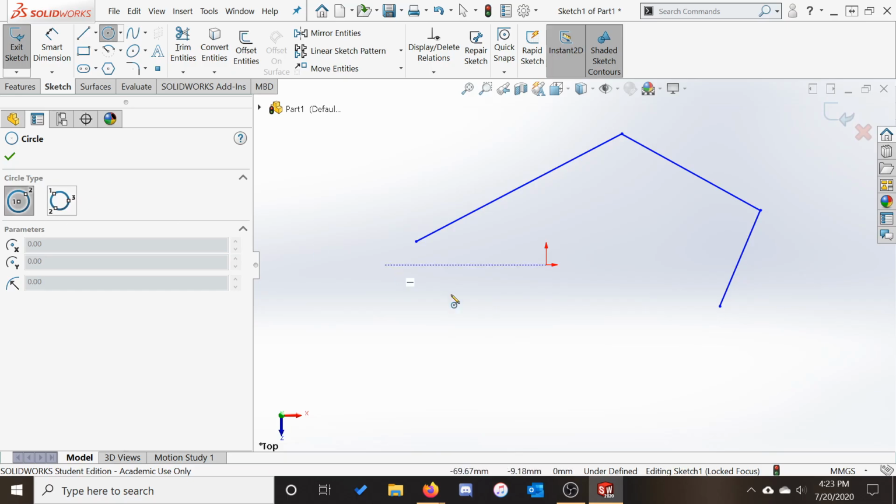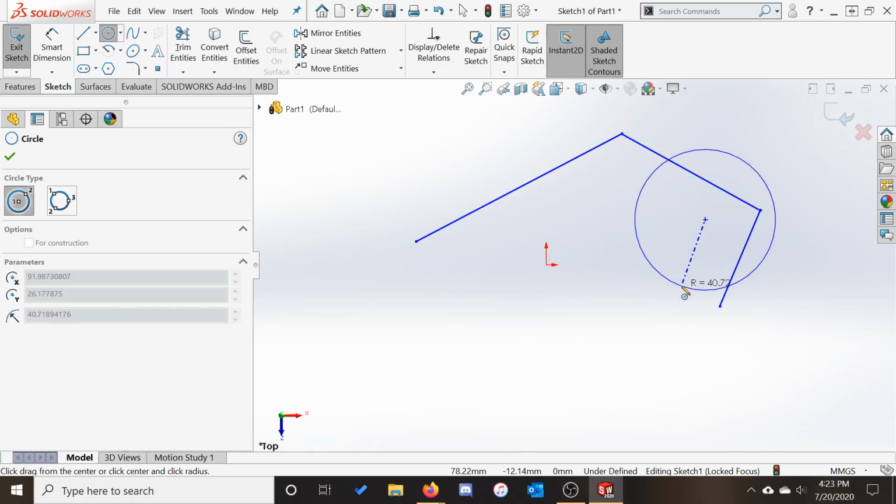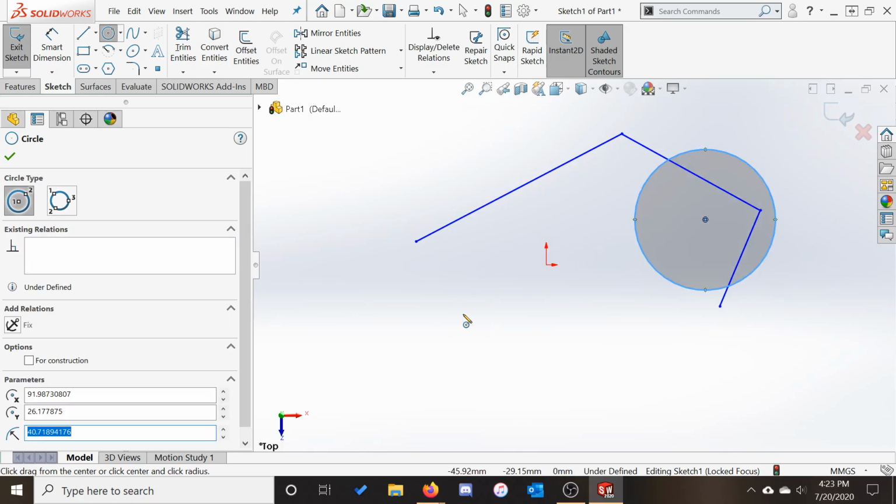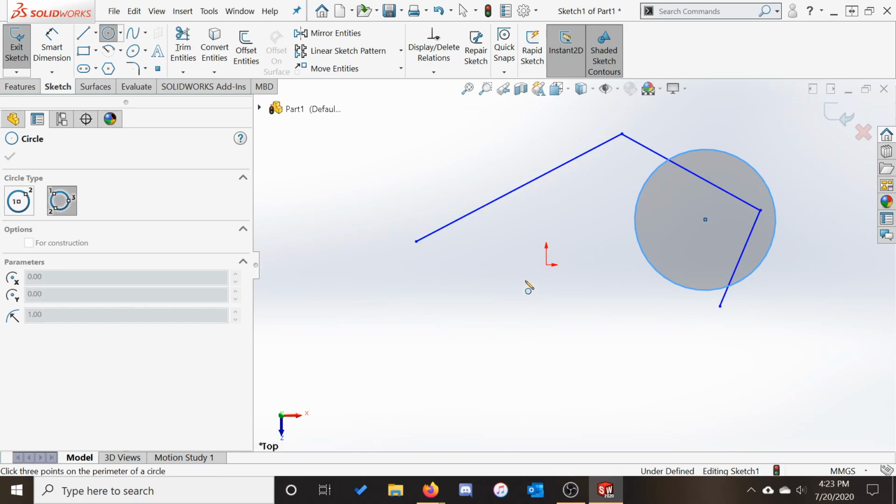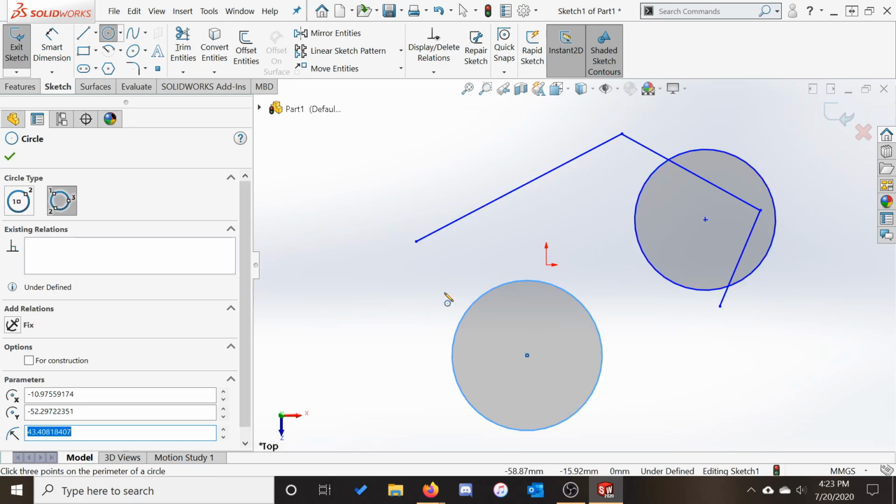For a generic circle, you can select the midpoint first by left-clicking, and then click again to set the extent of the radius. The other option allows us to draw a triangle. SolidWorks then generates a circle that hits all three of our points. We can go directly to our alternative methods by hitting the drop-down next to the tool.